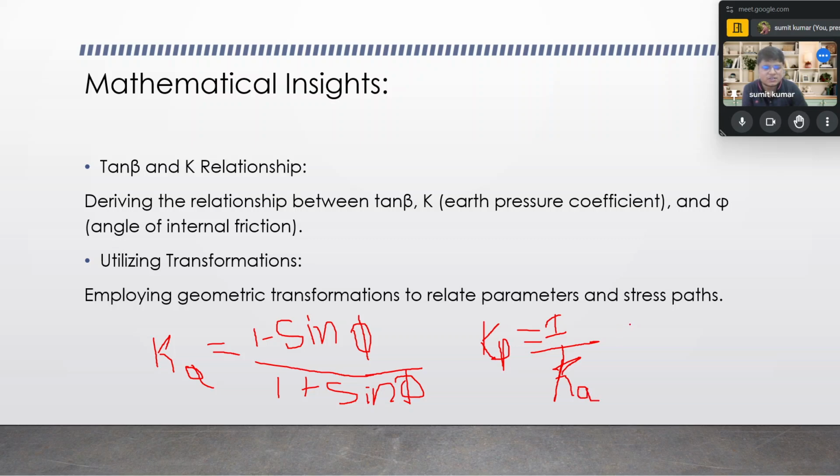For the earth pressure at rest condition, this is the active condition, the other is the passive condition, but there must be a situation when the earth is in rest condition. Over here K is written as 1 minus sine phi, or mu by 1 minus mu. Mu is the Poisson ratio over there as well, mu by 1 minus mu.